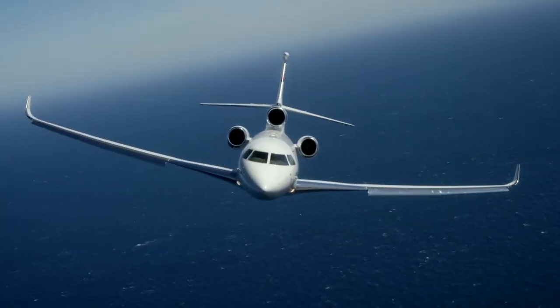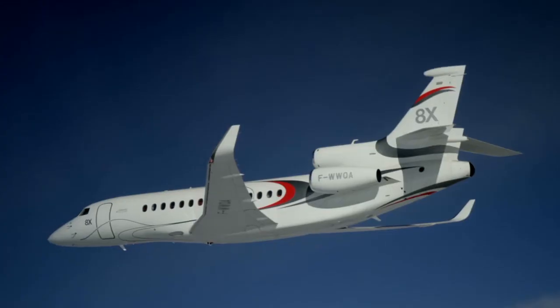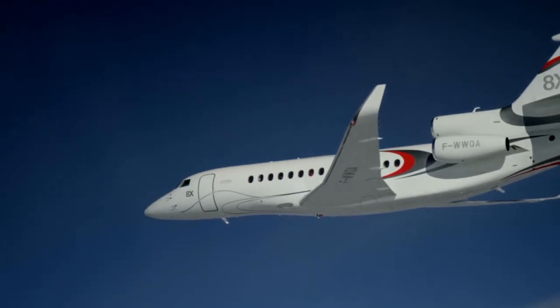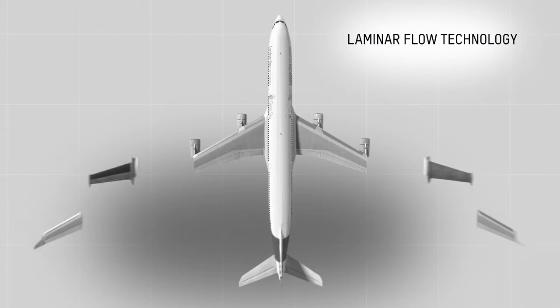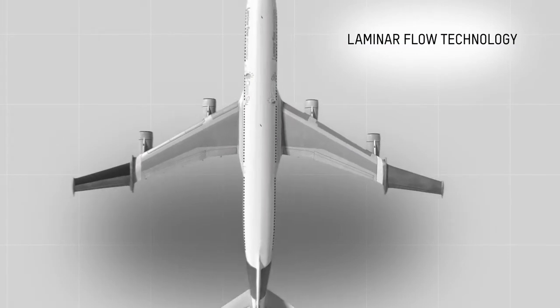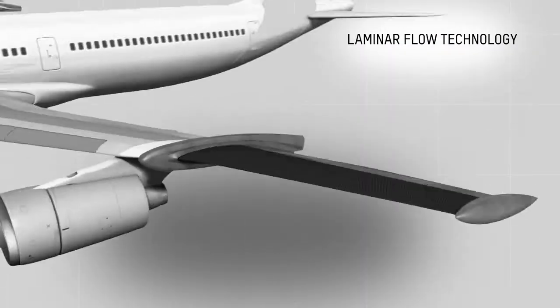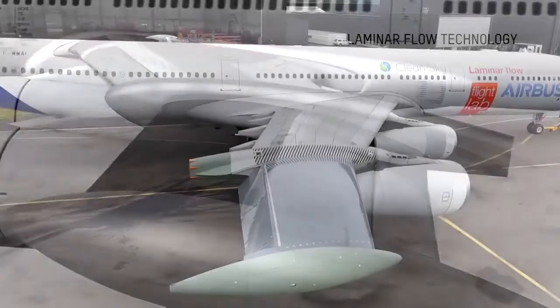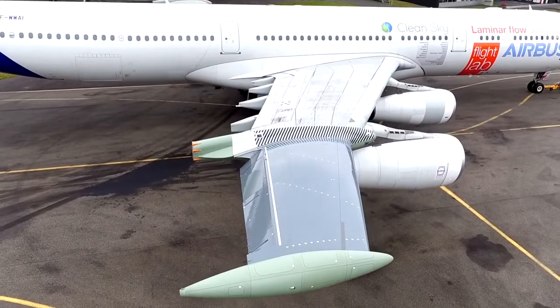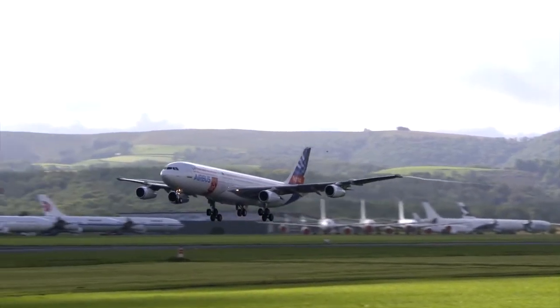The defined targets for the development of the future European civil aviation require more environmentally friendly and fuel-efficient aircraft. In this context, laminar flow technology is becoming more and more important as the laminar flow around the surface is characterized by lower friction than for turbulent flow, which leads to a reduction of aerodynamic drag and fuel consumption.